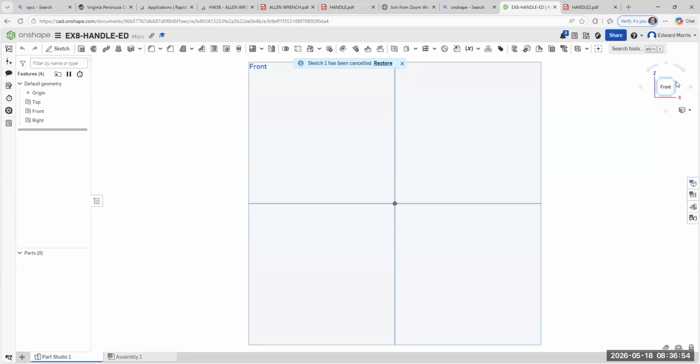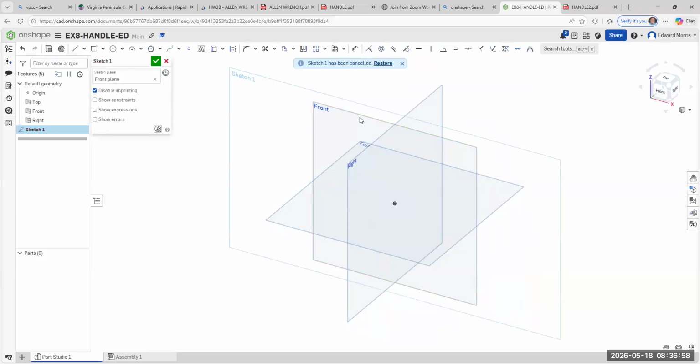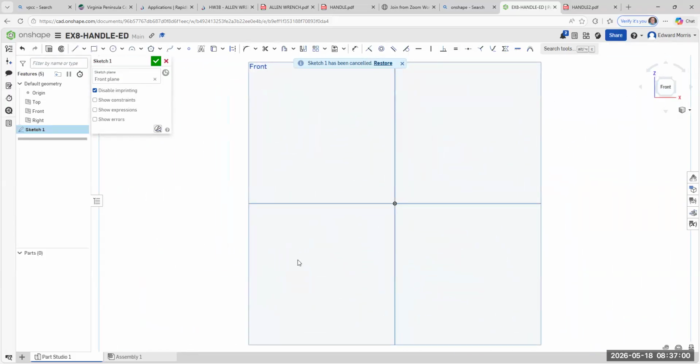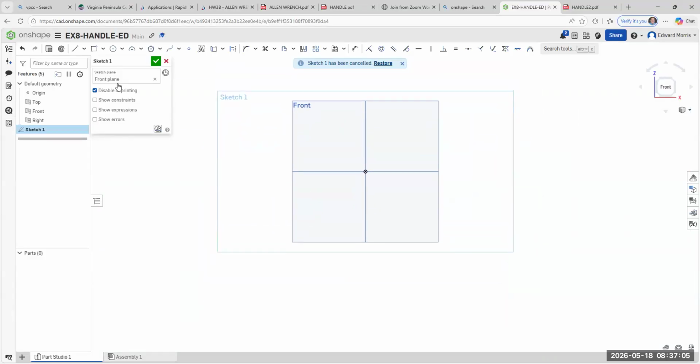All right. Now what I've got to do is redefine my sketch plane again. Sorry about that. I'm going to zoom out some. Now I'm going to go to the line function here, go to line. Now look, I'm going to snap to the origin. I'm going to come out to the left, click, and this is where we can edit the dimension.